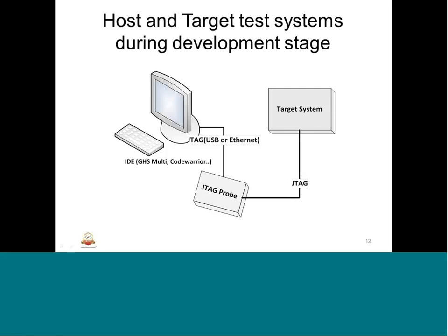There are tools which interact with this and allow the user to monitor or put in values. For example, integrated development environments include GHS (Green Hills Software), CodeWarrior, etc. The interface with the JTAG is usually through USB or Ethernet.